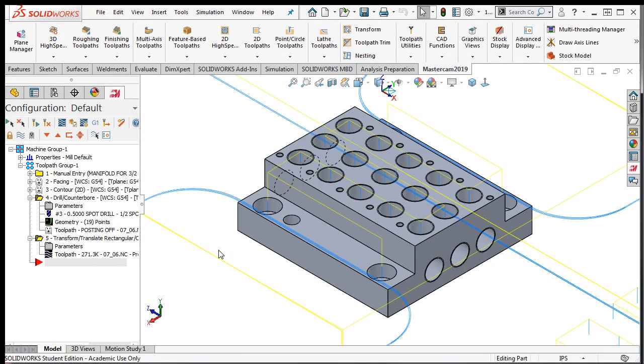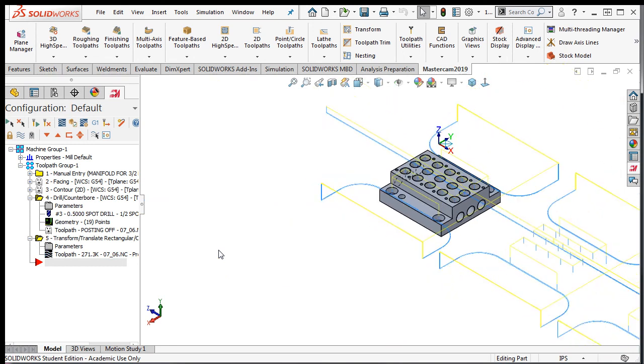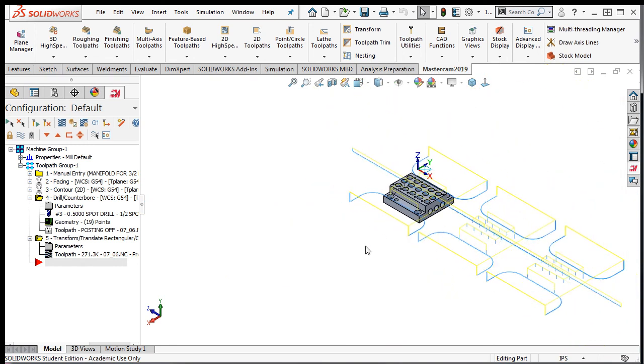And I'll zoom out so I can see all the cut lines. Notice how operations 2, 3, and 4 have a picture of a ghost. This means their code will not be sent to the machine. I'm happy with these toolpaths, so I'll save my work.